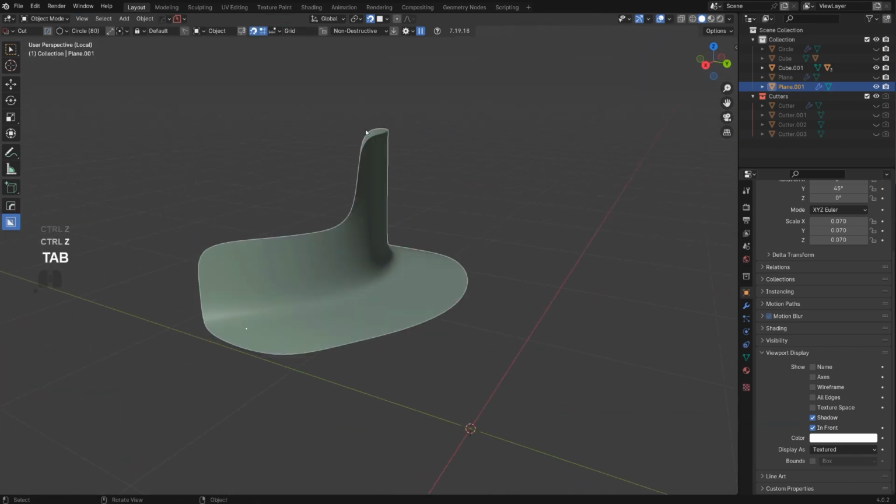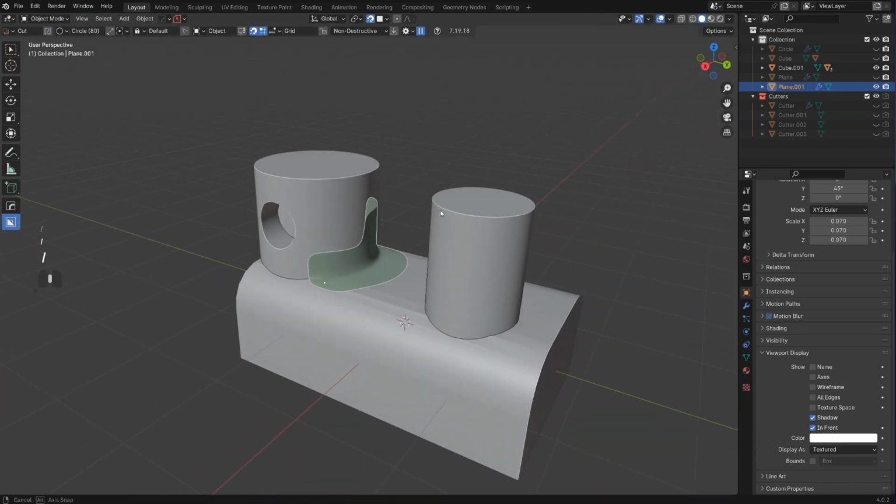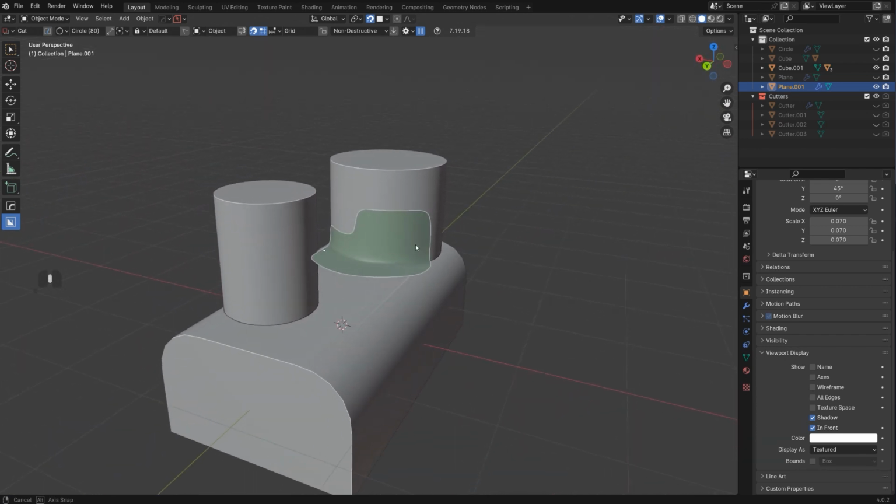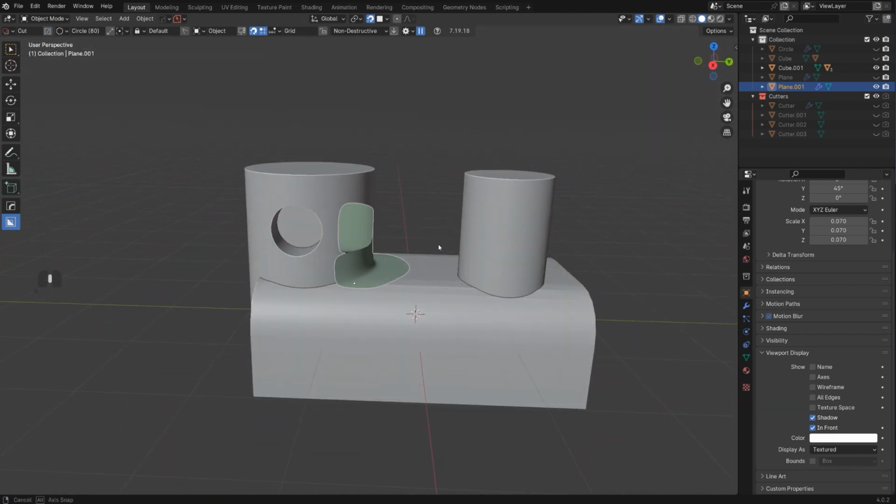So this is a really good method for very complex meshes, or meshes that are simply impossible to fix, like CAD meshes. Because when you import something from CAD software like Plasticity and you try to move any of the verts or change anything, you will have problems with normals and with shading, because these meshes come with custom normals and you can't really fix that in Blender, okay? So the retopology is going to be the only way to go about it.